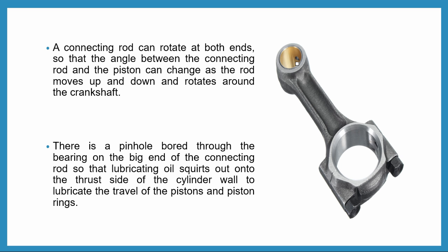Here you can see in this picture there is a pinhole. Within this hole the lubrication oil passes, and when the small end is connected with the piston pin, the oil squirts from the piston pin, which will help the lubrication of the cylinder wall.